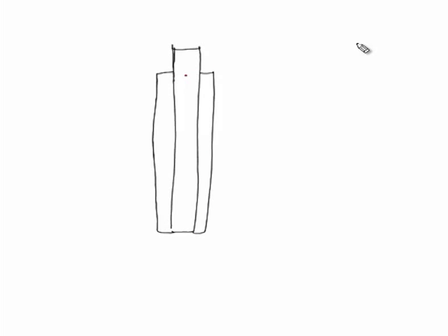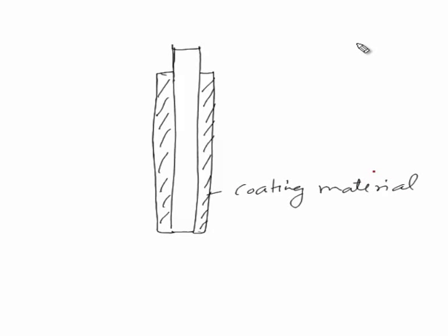So, outside we have the coating material, and this one is the core wire. This core wire can be made of the material which is to be deposited in the weld metal, may be similar to that of the base metal or may be slightly different in composition, especially when a different combination of mechanical properties is required in the weld joint for specific purposes.